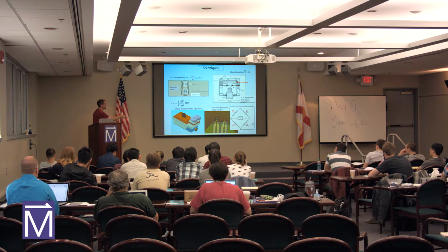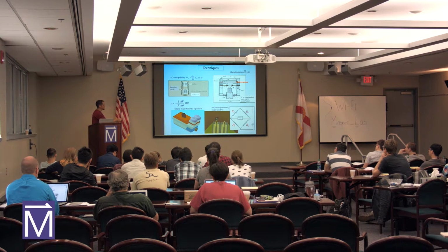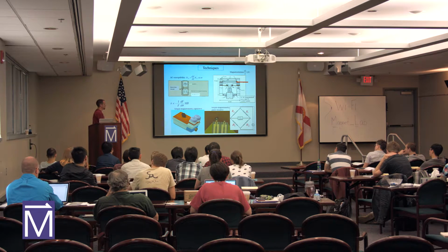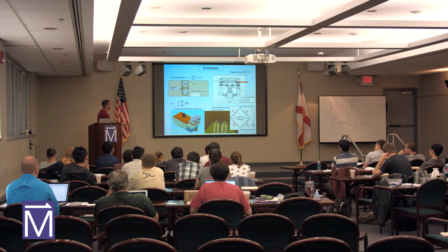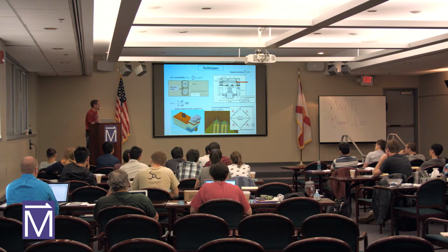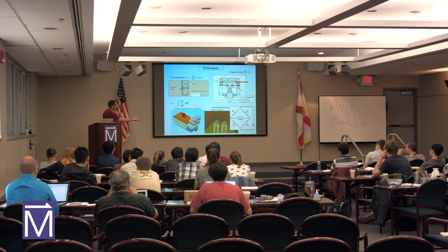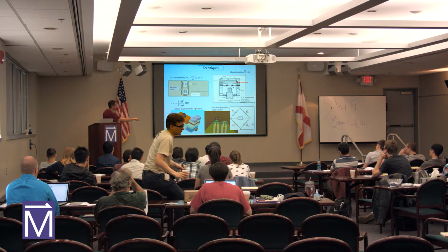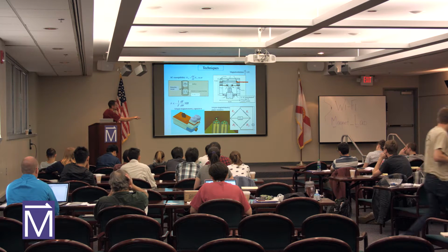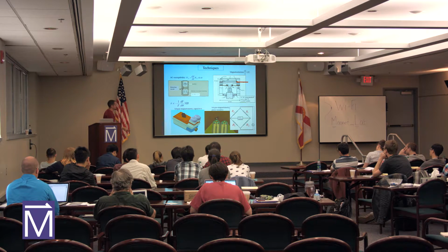So we also have these piezoresistive cantilevers. I saw Eric talk about them a little bit, but it's better to hear something twice than not at all. So these were actually developed as AFM tips. When you buy it from the company, it actually says on the box it's an AFM tip. But the way they were measuring the surface of a material with AFM was because of these changes in resistance. And the actual changes in resistance just come from these points where the lever arms are attached to the body. So there's a resistance path that goes up here and a matching one that goes here. So if this lever arm moves, then the resistance will change.